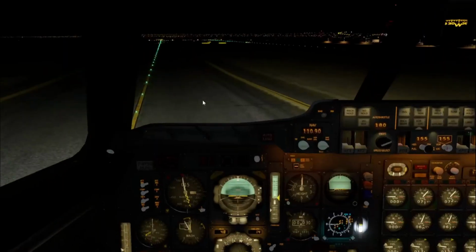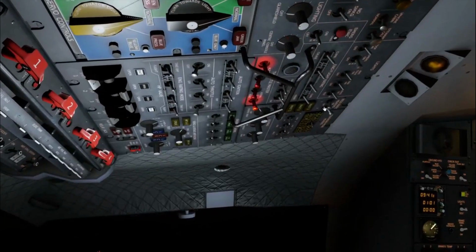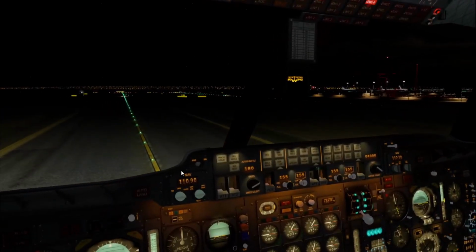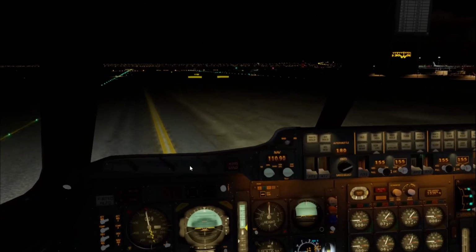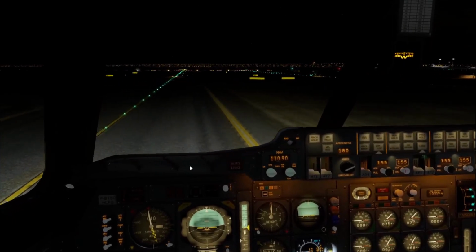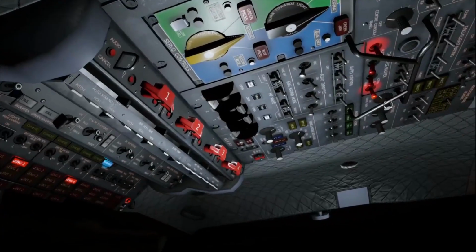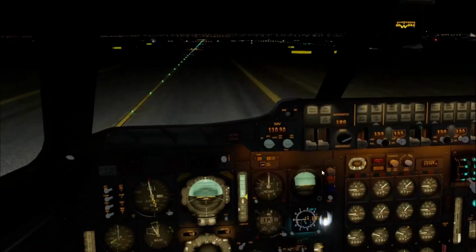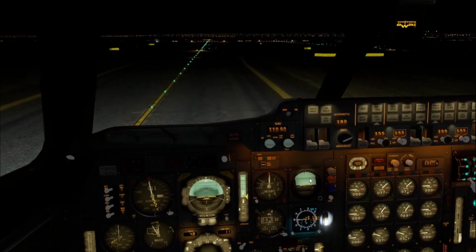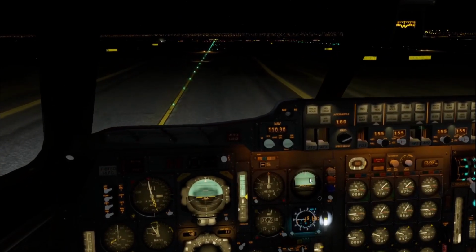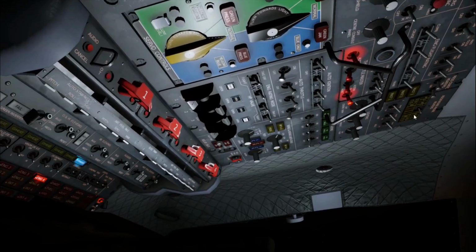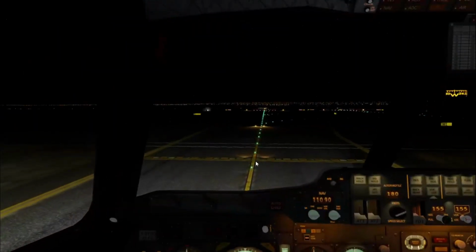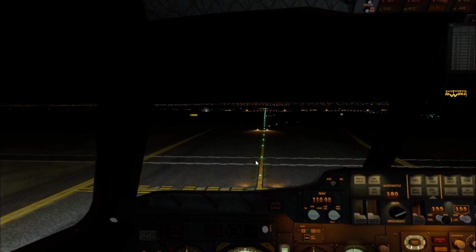What is the temperature here? 18. All right, we can switch off the heaters. For 18 we don't need them. This one can be set off. Oh, wait. This is on standby and inhibit. Inhibit means that if the temperature is above 15 degrees, which we currently have, you may have it at inhibit. If there is low temperature, there will be a warning.